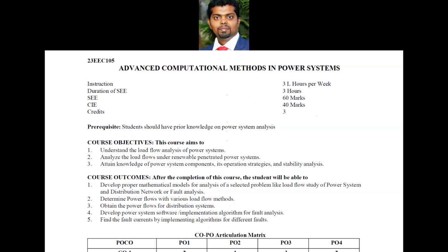The same thing applies to the unit commitment problem. Unit commitment is committing the generating units for a particular 24-hour period of time, which is a very complex problem. But what we are doing is making certain assumptions, that the load is not varying, the voltage is maintained constant, and the power is maintained constant. Like that, we make certain assumptions and try to attempt that problem.